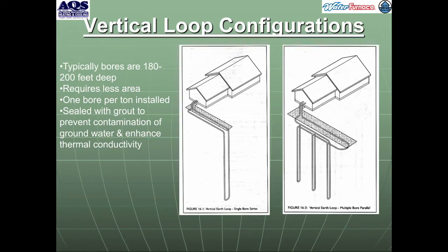every one of these vertical loops would be drilled down to a certain depth, and then whatever that ground is, what they would do is fill that with a grout. So they seal it with grout. So you're dropping the tube system down with a special 90-degree U or a U bend here, on the very bottom.